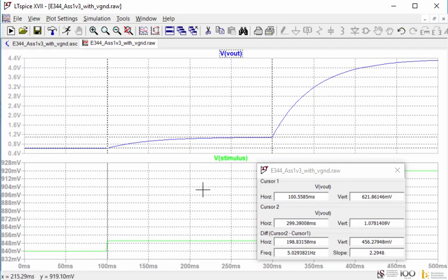So the noise will now be a bit higher. So you needed to find that perfect middle ground between finding the adequate step response and then filtering that enough. So obviously an RC filter seems to be able to do it. If it wasn't, then you had to use whatever other filter you had at your disposal.